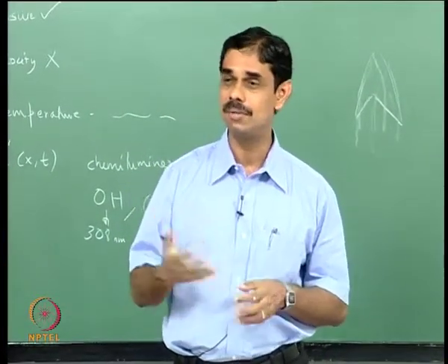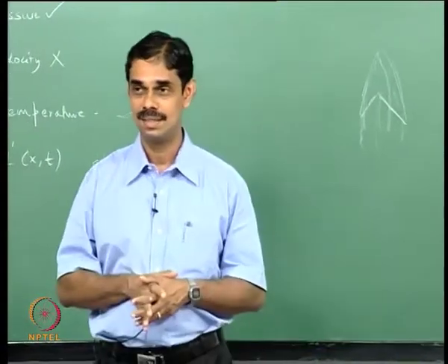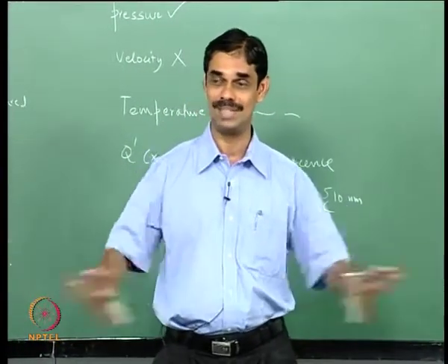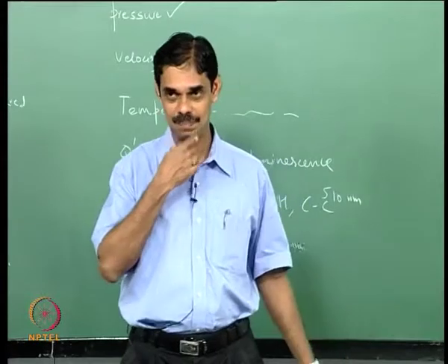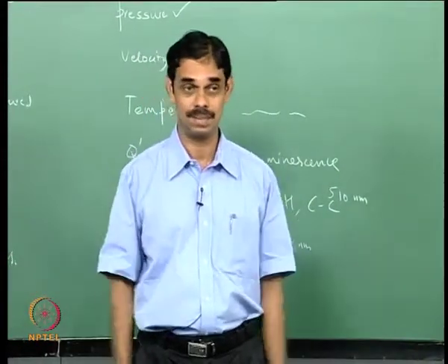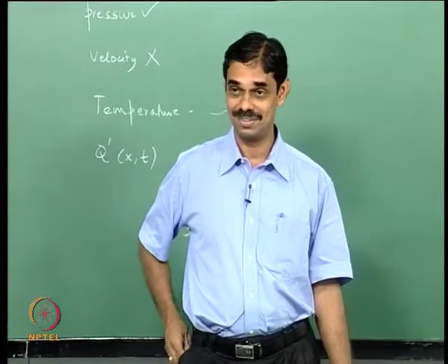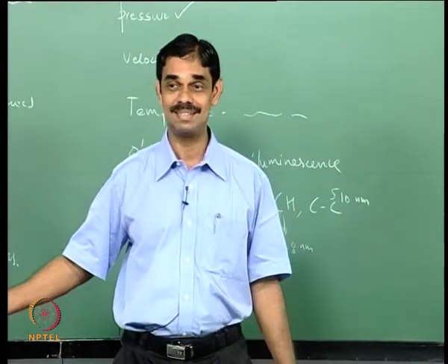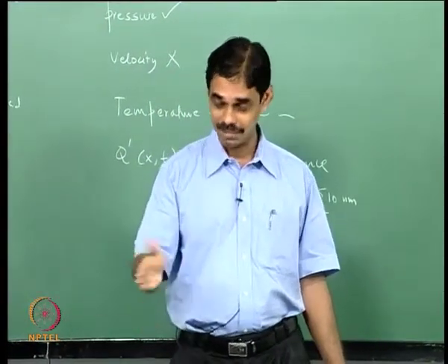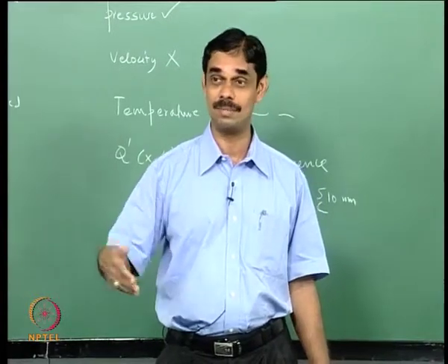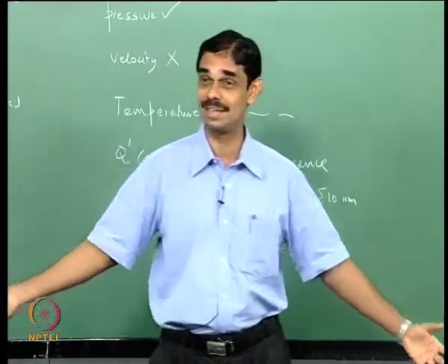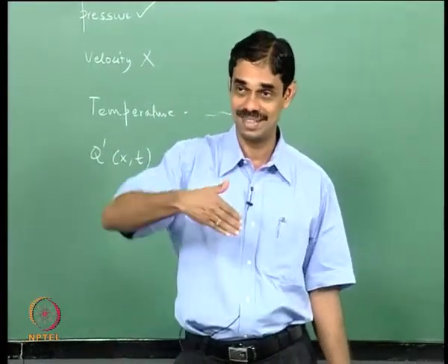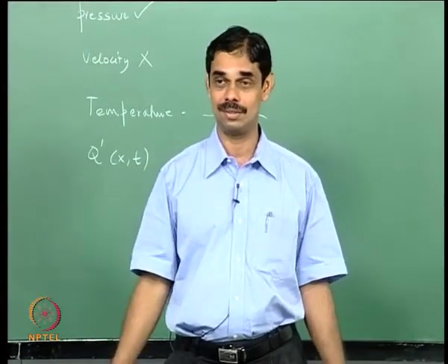Now if you speak to an engineer who designs combustors, not a thermoacoustic expert nor a control expert, but just a person who is worried only about combustion and wants the combustor to work, someone who designs engines or burners, he would say he does not want any active control. Even if it is the most lovely active control, it works beautifully, he will still not want it. First of all, you have to actuate, that means something has to work several times a second, and combustors typically run several thousand hours, sometimes years continuously without stopping, and he does not think any movable part can work that long without maintenance.